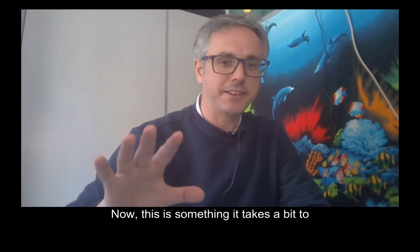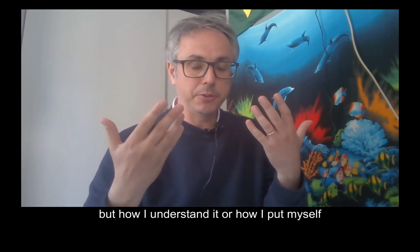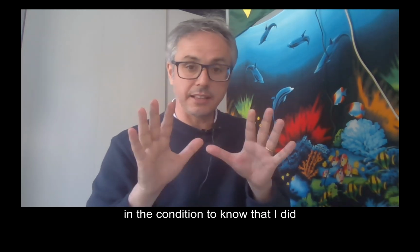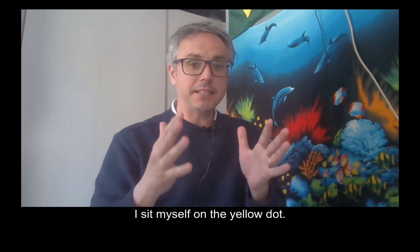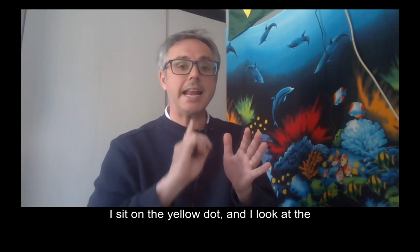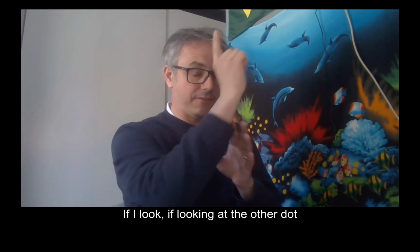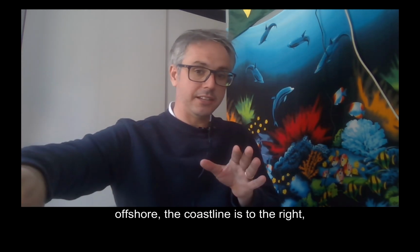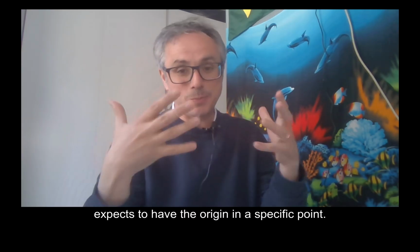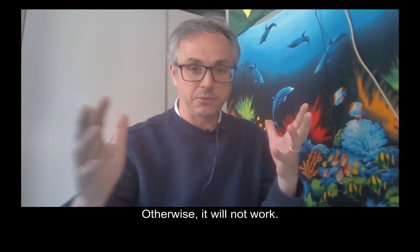Now, this is something that takes a bit to understand, but how I understand it, or how I put myself in the condition to know that I did everything right, is I sit myself on the yellow dot. I'm offshore, I sit on the yellow dot, and I look at the other dot that is offshore. If looking at the other dot offshore, the coastline is to the right, then I did it okay. Otherwise, I have to flip the grid. This is because XBeach expects to have the origin in a specific point. Otherwise, it will not work.